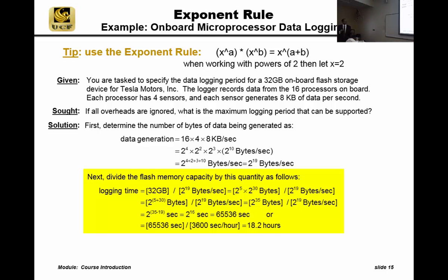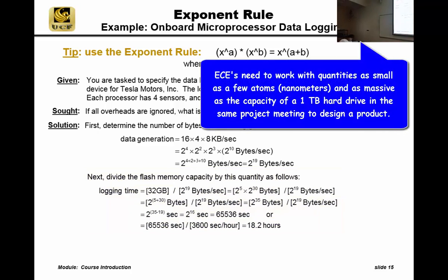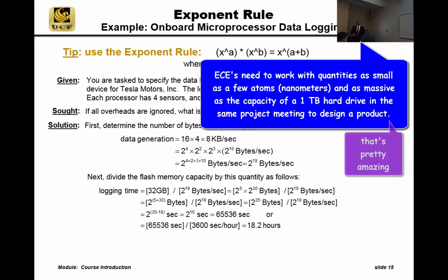What is that in human terms? Well, this is a lot of seconds. So human beings don't do well with big numbers, which is kind of the takeaway of today's lesson. As computer engineers, we work with nanometers. Especially electrical engineers, you buy Intel, it's a Broadwell processor, that's in that laptop. It's 14 nanometer technology. A nanometer is nothing. Actually, 5 nanometers is about 18 silicon atom diameters. That's nothing to build a transistor out of.